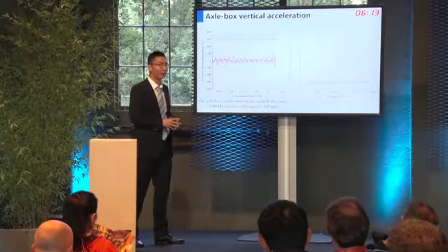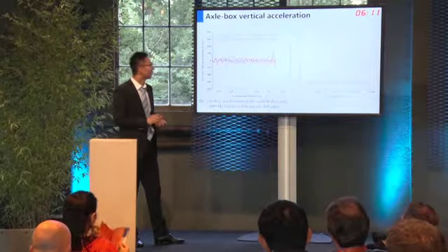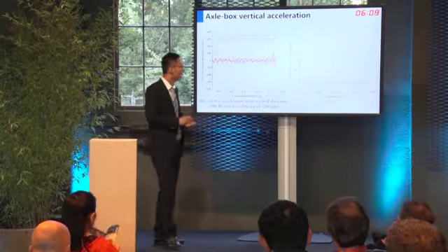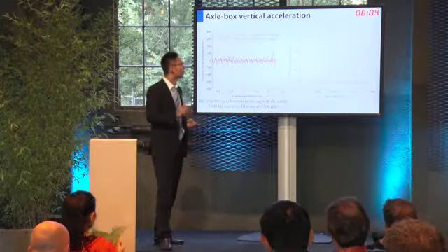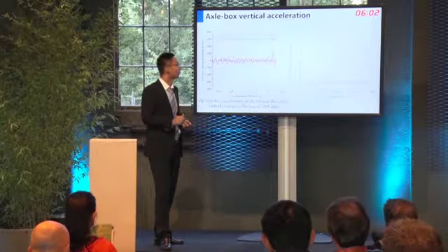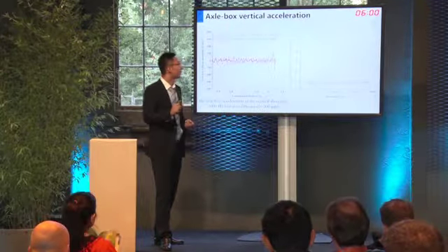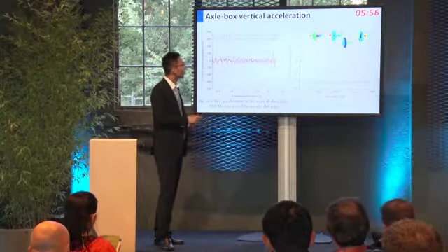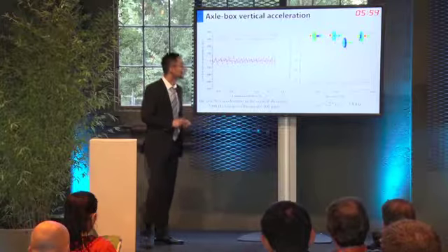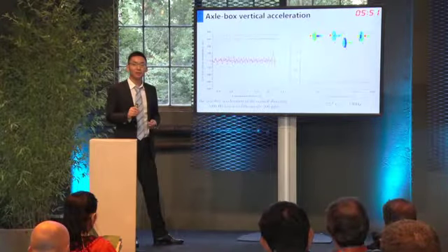The latter figure shows the spectrum characteristics. We can see that for the 31.5 millimeter wavelength, the maximum acceleration occurs at the excitation frequency of the corrugation. Other peaks correspond to the axle box resonance.